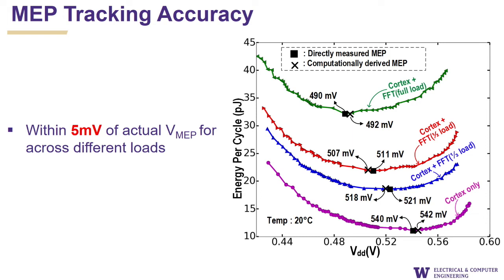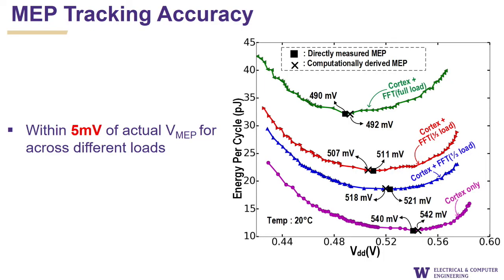You either operate with just the Cortex, which is just the microprocessor core, or you run it with the FFT that's throttled. And then you keep reducing the throttle until you get to the green curve where you're running the Cortex and the FFT is banging away at max frequency. Maximum switching activity, minimum switching activity, okay? And it's running whatever benchmarks ARM provides us while running this system.